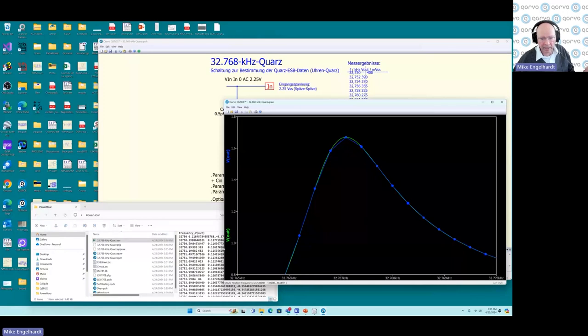You look at it, you see here's V out and there's V out. Well, which is V out? It's up to the user to keep track of this data. So normally, SPICE users don't do overlays. They do dot step, because that way the waveform viewer can be perfect.